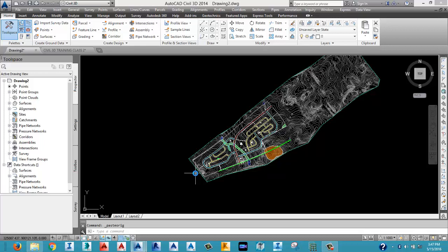When your surveyor moves to site, he captures the survey of the whole area in question. There's something called a demarcation survey, and something called a topographical survey. He's going to give the planner the demarcation survey, which gives the perimeter of the project site in question. Once he gives him the demarcation survey, the planner has an overview and understanding of the land use he has. Maybe he has 100 hectares, he has to work with 200 hectares. In the long run, the surveyor goes to pick the topographical survey, which gives the planner a full understanding of how the ground looks.